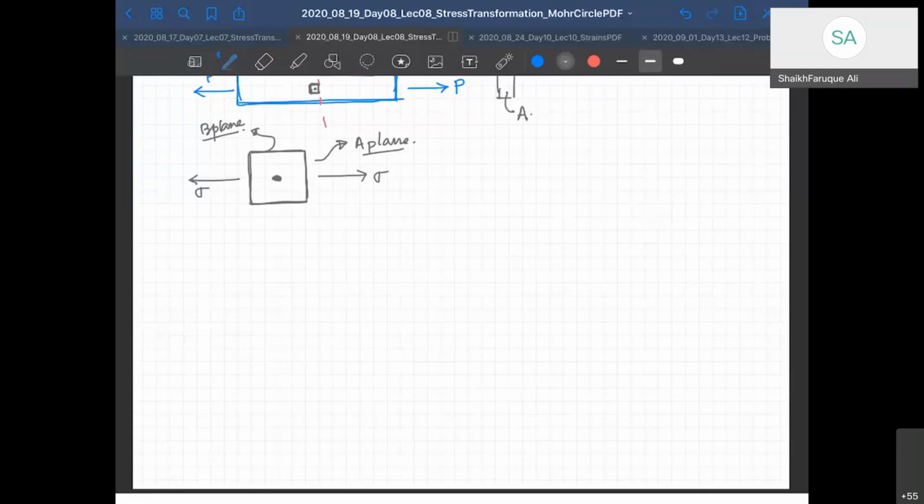For single directional stress, I'll tell you that it will go into plasticity. Once it crosses the yield, it will fail. It's a brittle material, so it will fail after its yield stress. All those things we can talk about maybe in 2 weeks' time. After that, there is a part of the course called failure criteria, so we will discuss those things in the failure theory part. Right now, can you draw the Mohr circle for this? All of you, is it possible for you to draw it?